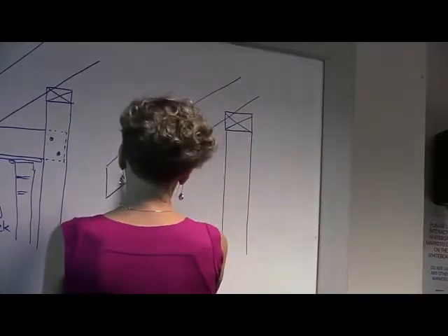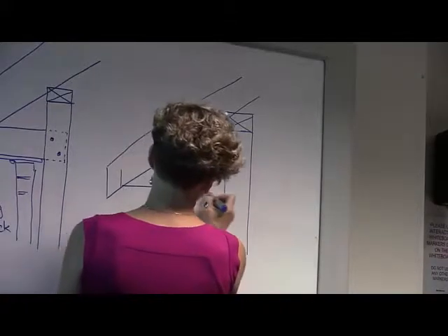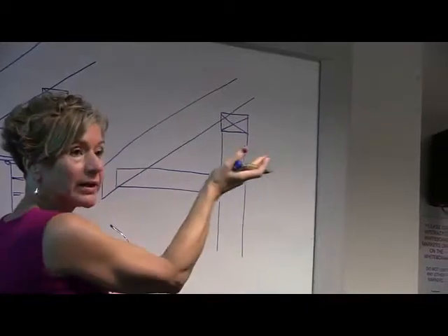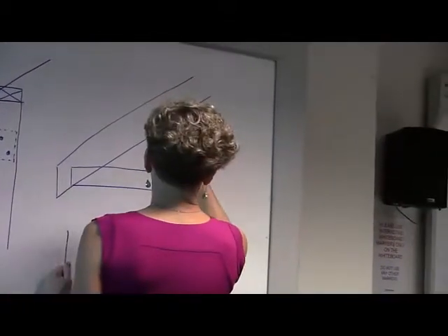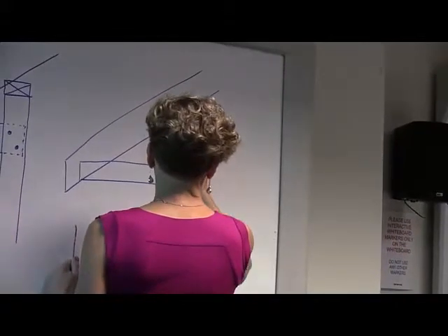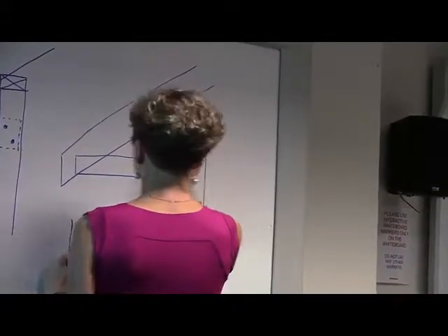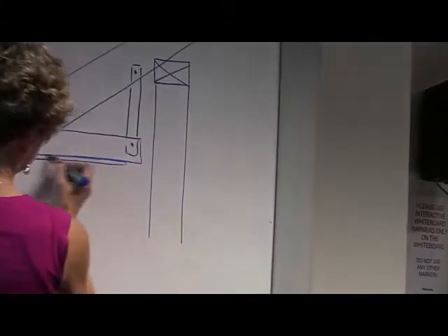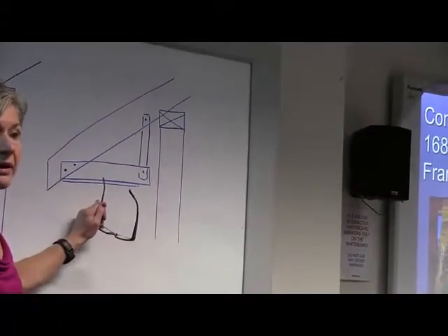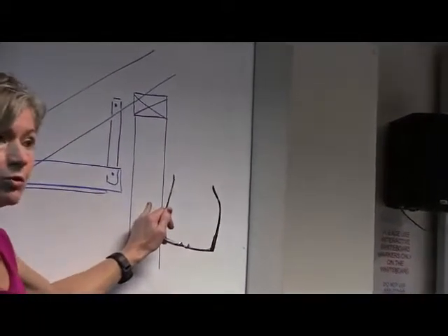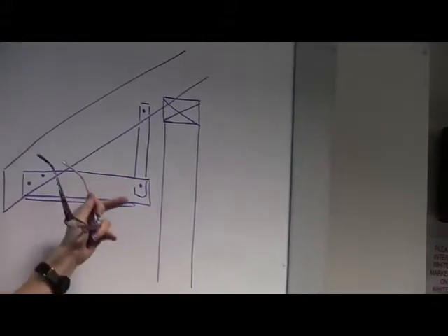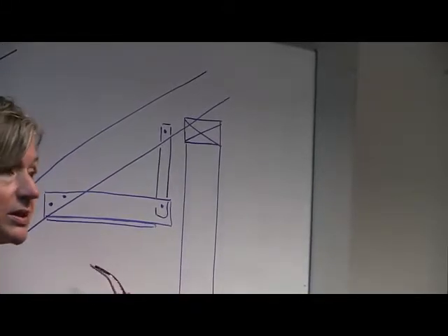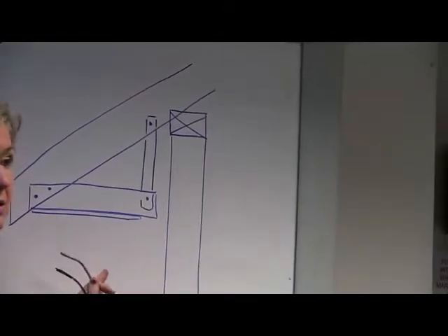what happens is you'll have a soffit bearer, in other words a timber member that you can attach your lining to, but it just sits from a little hanger and you apply your lining onto that. Alright, now that's not tied back. That's not tied back to your wall frame, and so this thing is still flapping around. Okay? So in this case, you would still need to consider what your overhang dimension is in sizing your rafter.